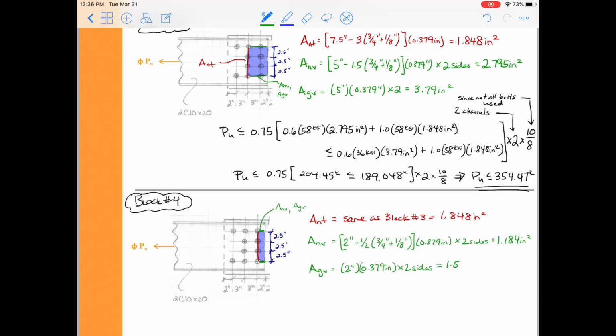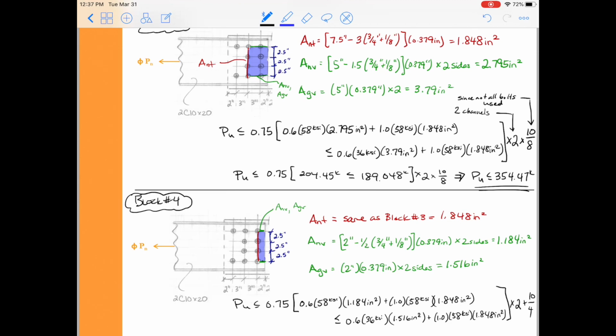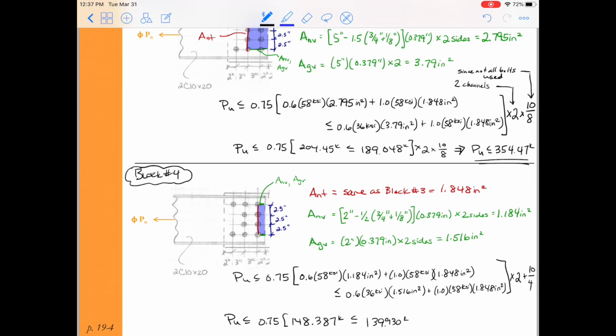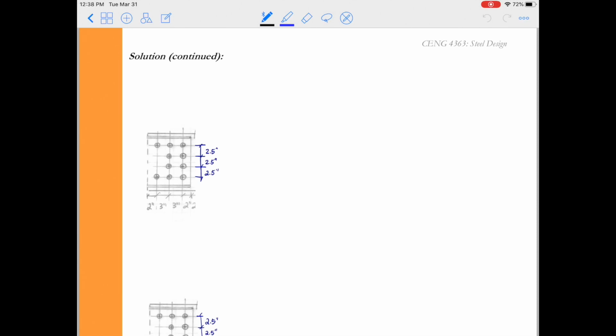Hope you're killing these calculations. Don't forget, whenever you consider blocks that are behind the front line of bolts, we have to use that multiplier to increase because it's not the same load as was considered in blocks 2 and 3. Finally, don't forget to check the gusset plates.